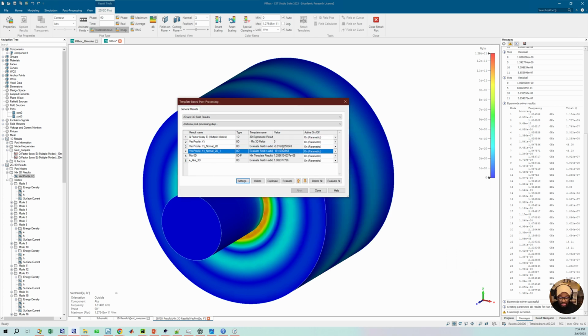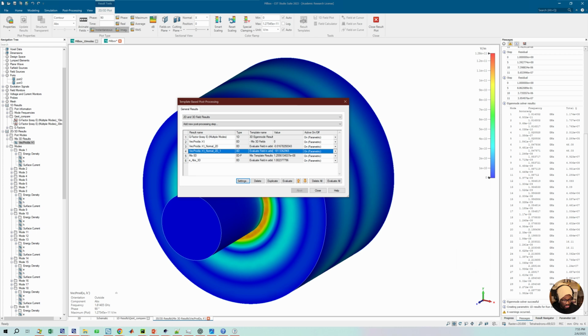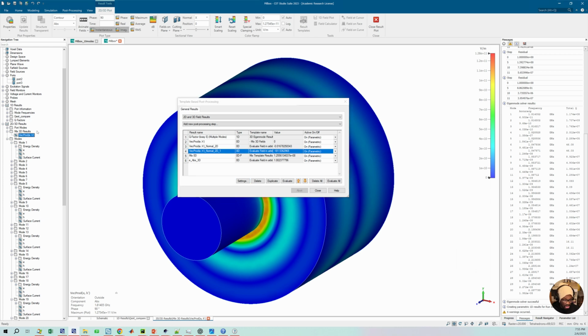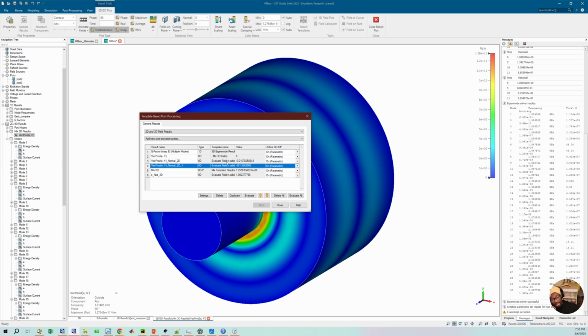So you see that for your trapped modes, you also have very different power flowing through the ports, even though this should be symmetric and you should have exactly the same amount of power flowing through each of the ports, but you have this much difference. So just be careful with the external quality factor calculation, irrespective of the method. If you know of any study that has benchmarked the numerical simulation with some experiment, so that we know which method is most likely to give you the right result, please share it.